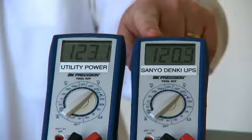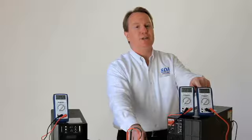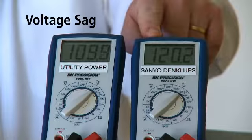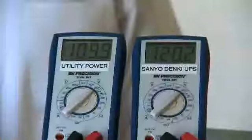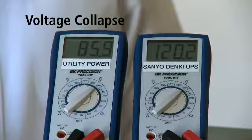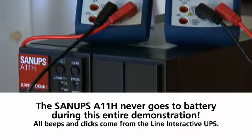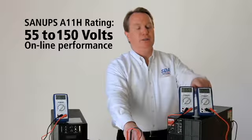Let's come down off of that. Let's go back up. Let's sit at the spike a little bit. Let's visit that spike a couple of times. All right, we have high instability in the utility today. Let's go down into a sag condition. As we get down into our sag condition, please notice our output voltage. Now we collapse. This unit is rated for 55 to 150 volts of online performance. There we are, 55 volts. Has there been any change?